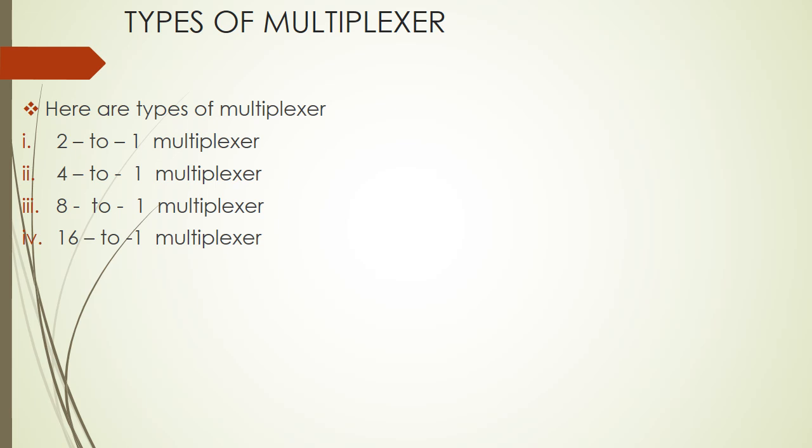If it is 4, we provide 0 0 1 1, then 0 1 0 1. If it is an 8-to-1 multiplexer, we provide 0 0 0 0 1 1 1 1 for the A side, then 0 0 1 1 0 0 1 1 for the B group. So that's how the truth table of the multiplexer functions.